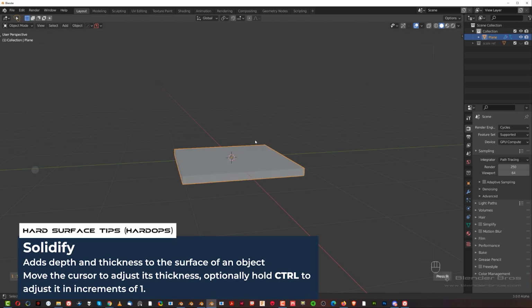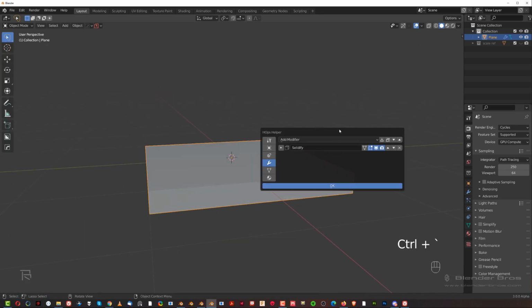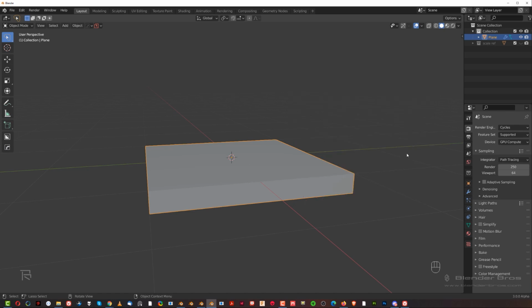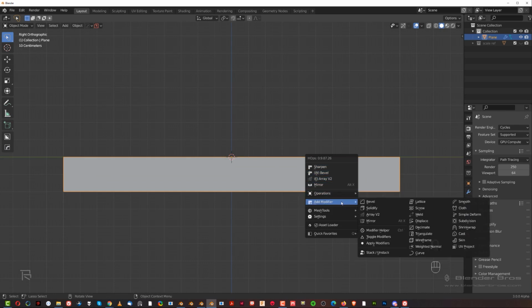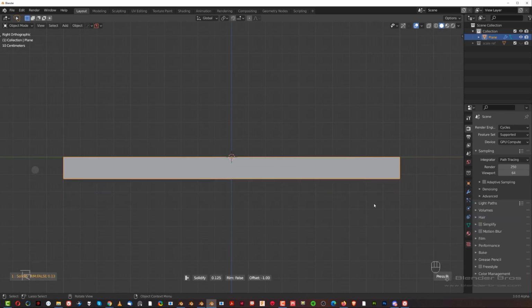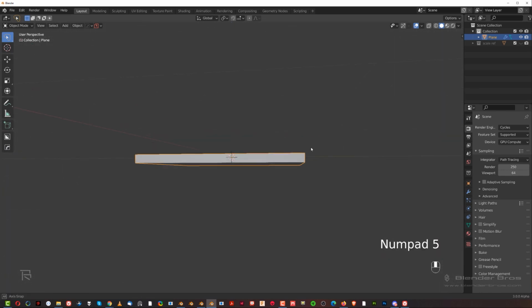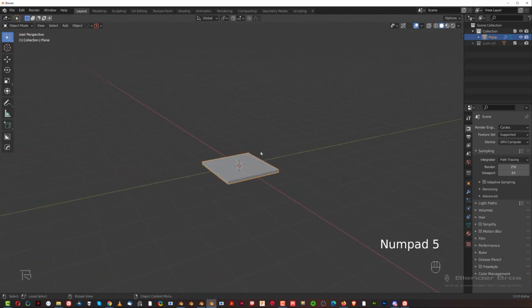and then when you move your mouse to the left, hold Control, and it's going to snap, you see, to a perfect size of 1, or in our case -1, because we're solidifying downwards. So you see here, thickness 2, offset -1. Now thickness could be 1, to be honest, doesn't have to be -1. We could make it a little bit less thick, so go to solidify and Control, boom, you're going to snap to just perfectly 1 grid, which is basically 10 centimeters. Okay, these things are important.